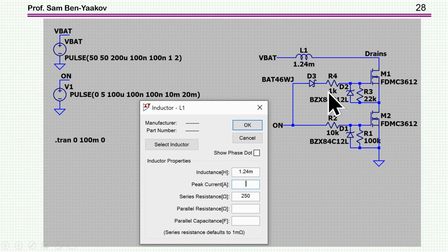with 1K here. Remember that we have here actually a voltage divider. So if you have here 5 volt, there's a drop on the diode, there is a divider here, so you cannot have this resistor R4 too large because you lose the voltage here at the gate, okay? Here it's okay because we have a 100K and actually there is no diode here. So this is the reason for the selection of these components. I've chosen this transistor, I'll talk about it in a minute.